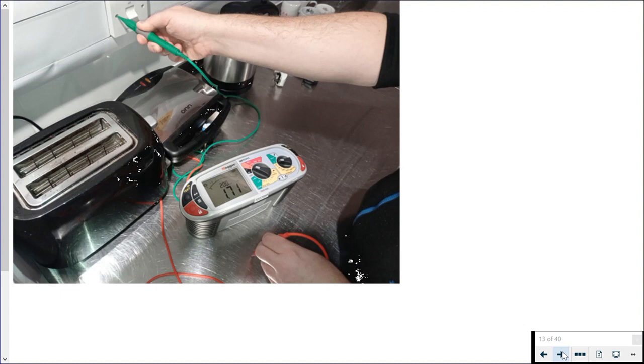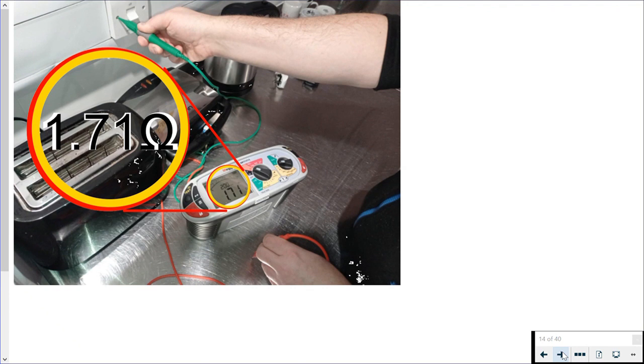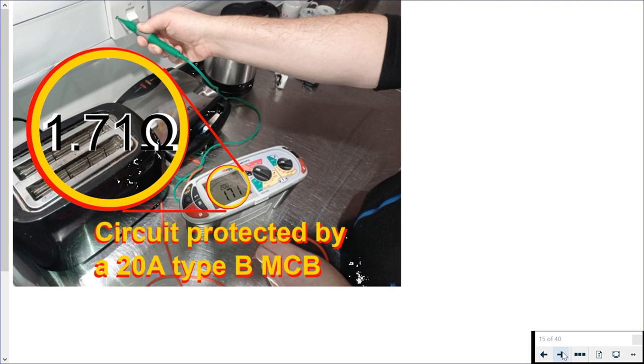We have measured between this switch and this worktop here on the continuity setting on our meter after zeroing our leads. We've measured a resistance of 1.71 ohms between this switch and this worktop. Okay, just a continuity test, 1.71 ohms. Upon further investigation, we identify that the circuit there is protected by a 20 amp type B MCB.